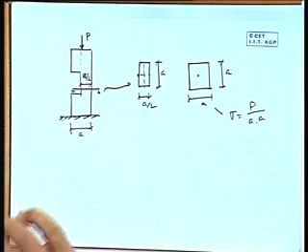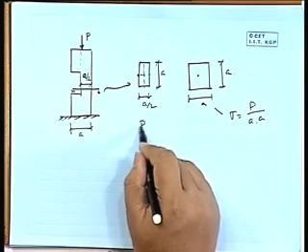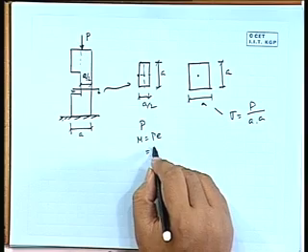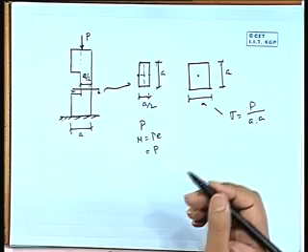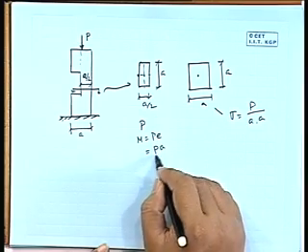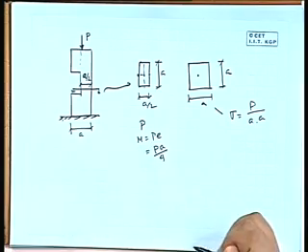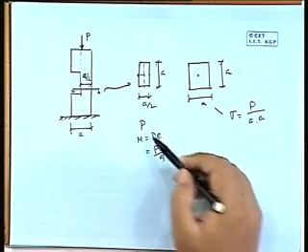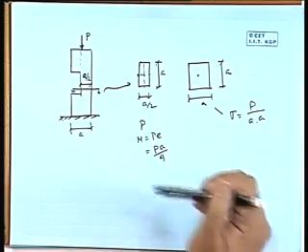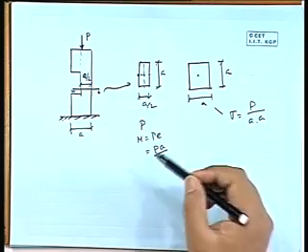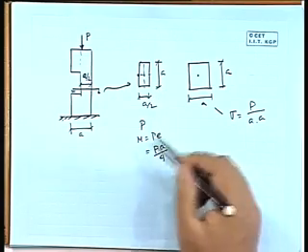So here there will be a moment. So the load is P and the moment is P into E. What is E? E equal to A by 4. Right. Now P into E, so P A by 4 is M. Now for that cross section, P divided by area, here it will be A square divided by 2, and this P A by 4 is the moment.